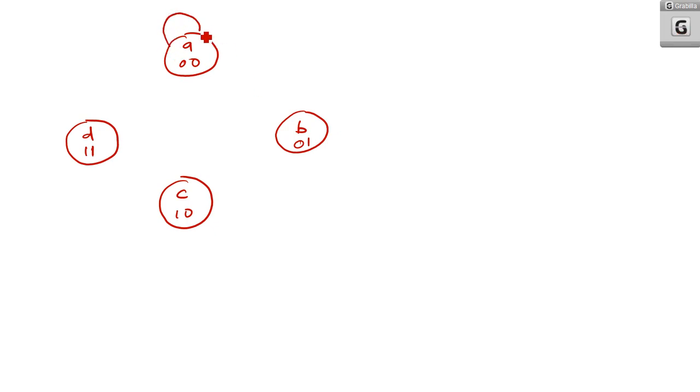Okay. Now in that case, I am given the input as 0. The first case is jumping to it. Input is 0. Then output also can be 0. That means the output of the state machine can be 0, but it will remain in state A. Again, here what happens? It will toggle from A to B if input is 1, but the output remains 0 itself. Again here, I can make it like this. That means input is 0 and output is 1. It will remain in B itself.